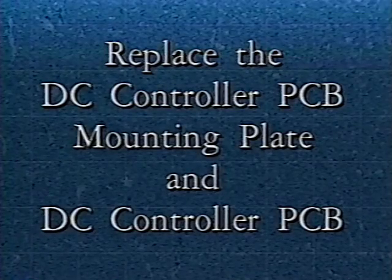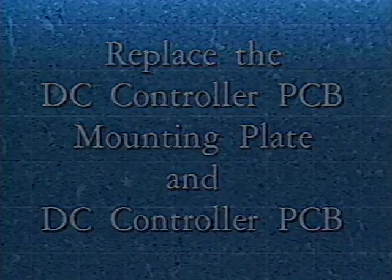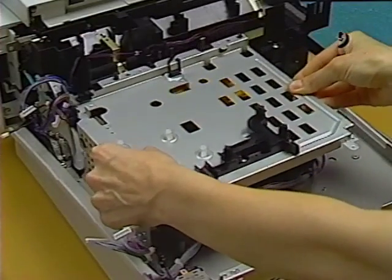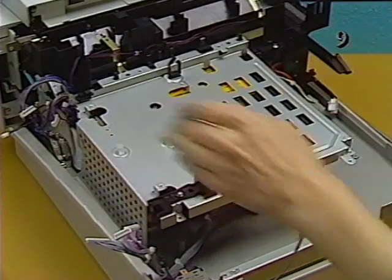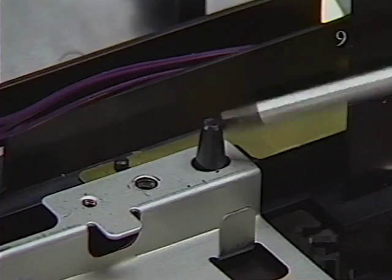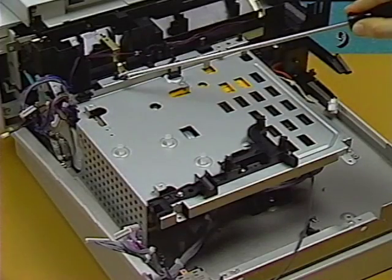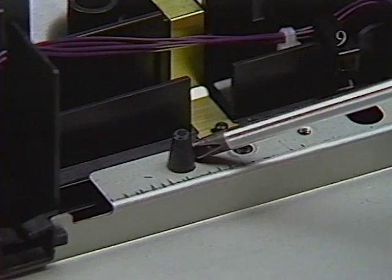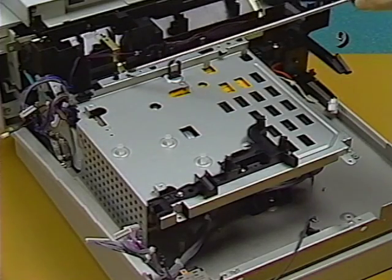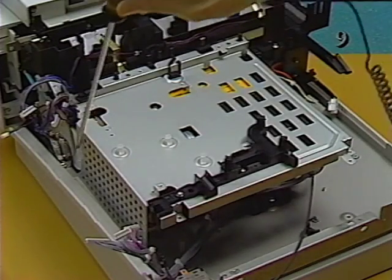Replace the DC controller PCB mounting plate and DC controller PCB. Start by replacing the DC controller PCB mounting plate. Make sure that the 2 cutouts on the mounting plate fit over the 2 positioning pins on the inner cover. Then replace the 4 screws that secure the DC controller PCB mounting plate to the printer chassis.